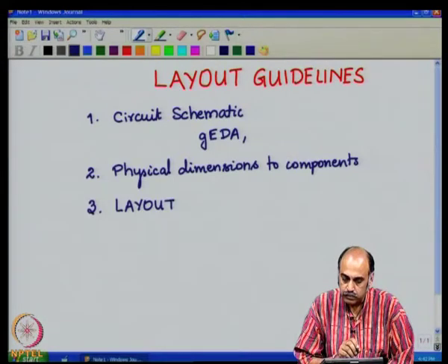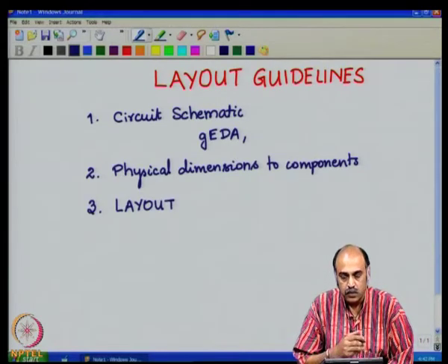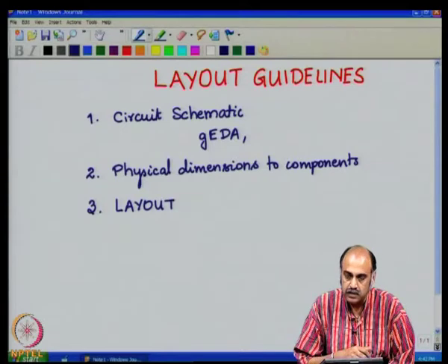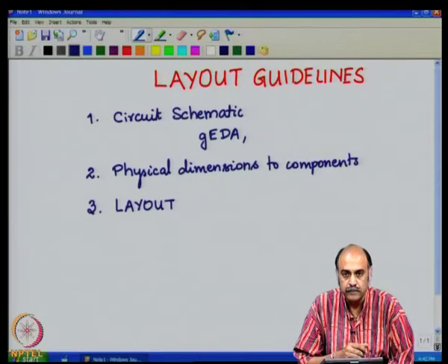Now, while we are at the layout, I should mention that the printed wiring board dimensions will actually come from the application. So, you should be pretty clear where this particular printed wiring board is going to be applied or where it will ultimately be mounted. Maybe it would be mounted in a 19-inch rack, or it may be mounted onto a custom enclosure, or it could be an extruded enclosure.